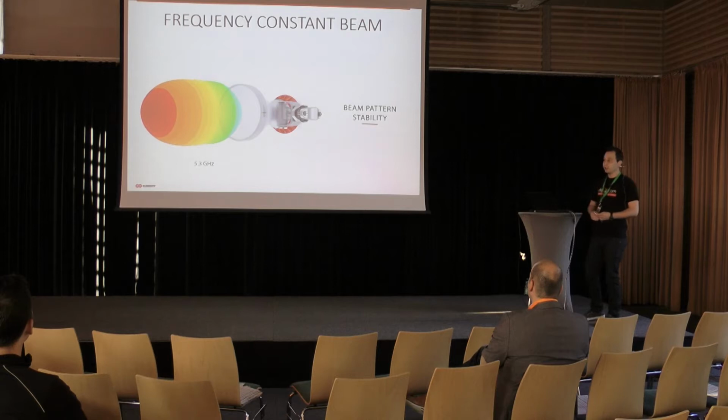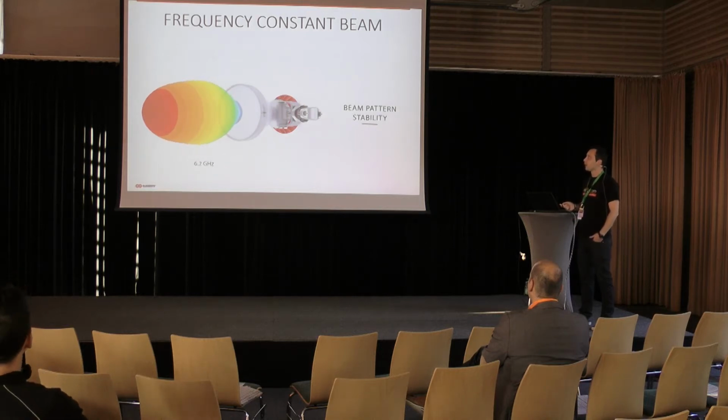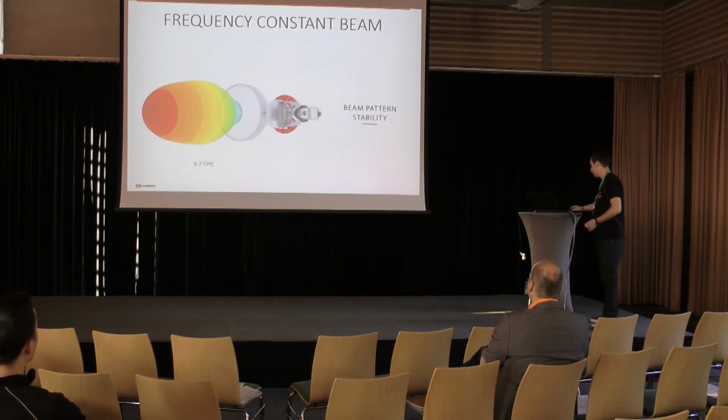The other huge advantage of the symmetrical horns is a frequency constant beam. So as you can see, with the change of the frequency, the main lobe of the antenna is still the same.